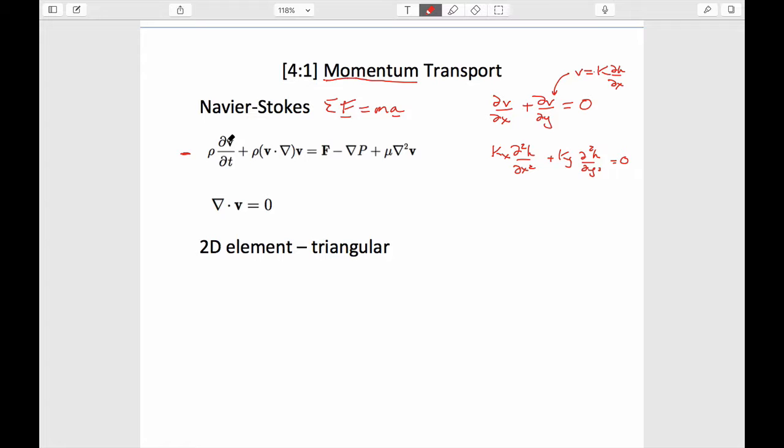And if we have behavior in three directions, and accelerations in three directions, and forces in three directions, then equally we have velocities in three directions. You see this is slightly bold here. This is actually velocities x, y, and z. Forces would be the body forces which are applied to our system, which would be the unit weight of the fluid, which is a known. This is a velocity, this is a viscosity, and we have another component which is the fluid pressure at a point.